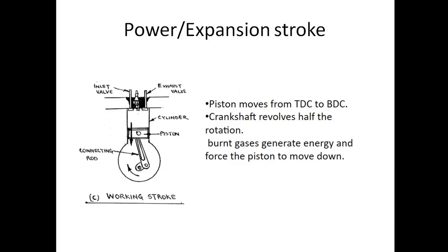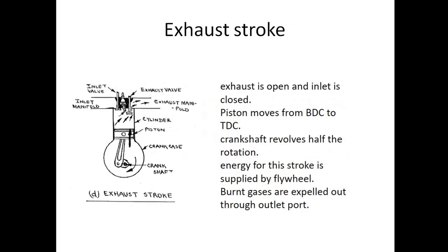This is the power stroke we have already discussed. Then this is the exhaust stroke. During the expansion stroke the piston comes to the bottom dead center. When it reaches the bottom dead center, the exhaust valve opens instantaneously, and the heat inside the cylinder is rejected to the atmosphere at constant volume, with the piston remaining at bottom dead center. After that the piston will move from BDC to TDC, expelling the byproducts of combustion, and once it comes to the top dead center,